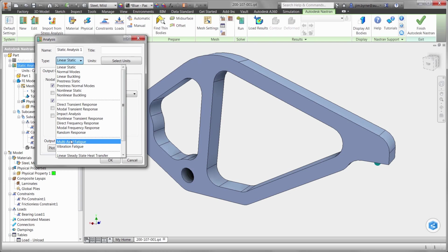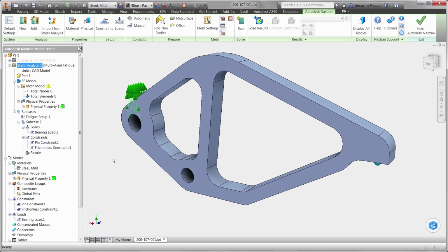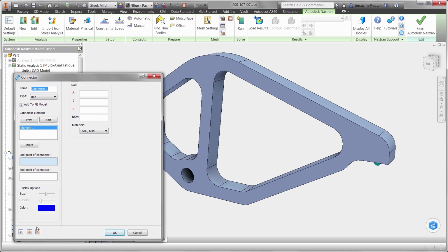We could run a linear static study and simply test for stress and displacement, but that's not going to be enough. We need to know if the clamp can withstand 300,000 load cycles. This requires fatigue calculations. There are numerous ways to constrain and specify the boundary conditions.